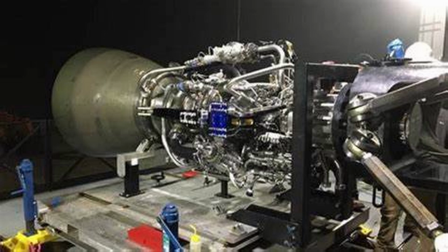Those alloys have the advantage of being specifically adapted to the area in the engines they are used at, and SpaceX knows every property of the material since they developed it themselves. Additionally, the Raptor is among the first engines to be at least partially 3D printed. About 40% of the early development engine's mass was 3D printed material.